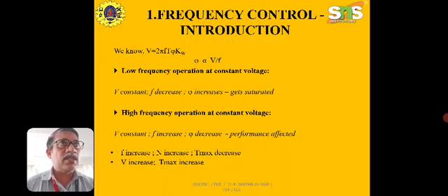If the flux decreases, we know the operation of an induction motor, the RMF flux decreases, then the performance gets affected. Therefore, frequency alone can't be utilized for varying the speed to a large extent. Please make a note of it, to a large extent.